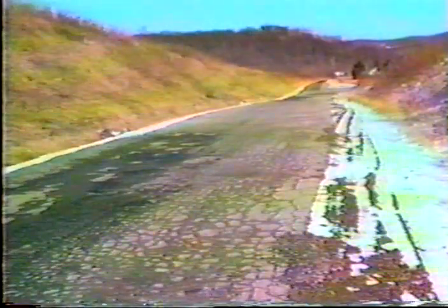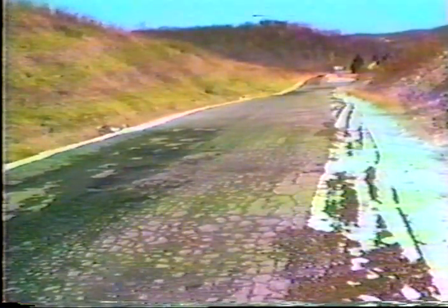subgrade. Open cracks allow water to enter the pavement structure. Water in the pavement then leads to base failure, potholes, and eventually complete pavement failure. Roads with cracks wider than 1/4 inch should be scheduled for crack sealing to prevent the infiltration of water.